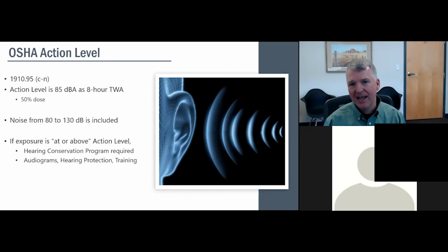And again, the original noise standard with those requirements to do monitoring in that form with those settings is in place, and the requirement to do the monitoring with the noise dosimeter with 80 decibel threshold in order to compare your results to the action level. So there's two things going on here now that you have to do.